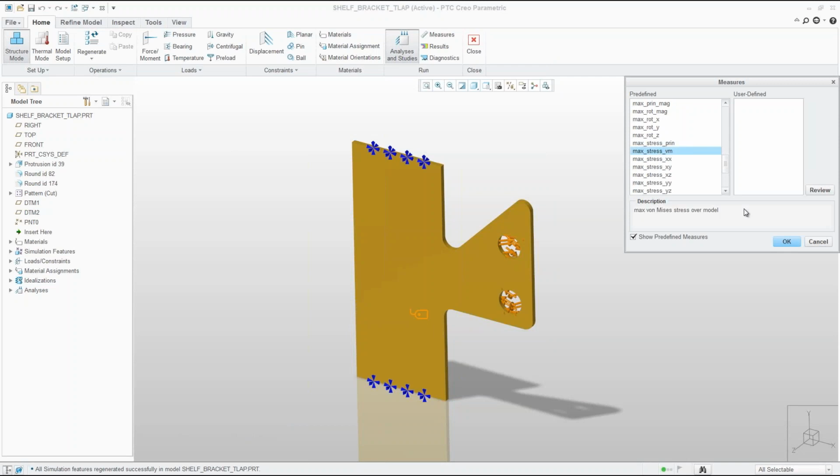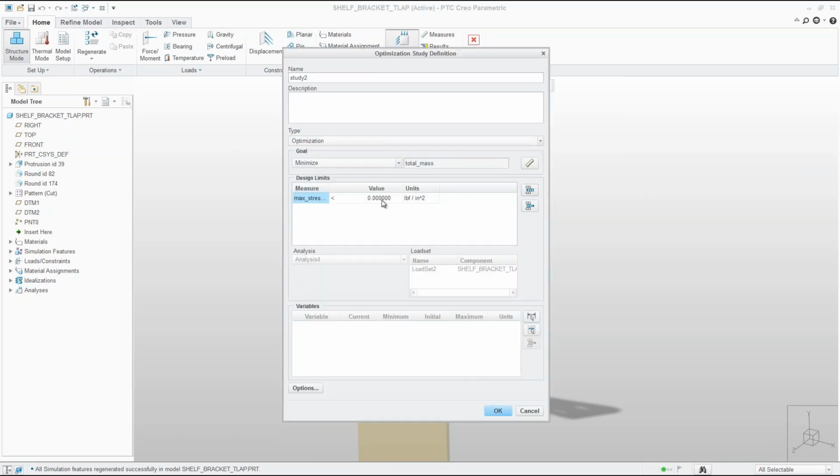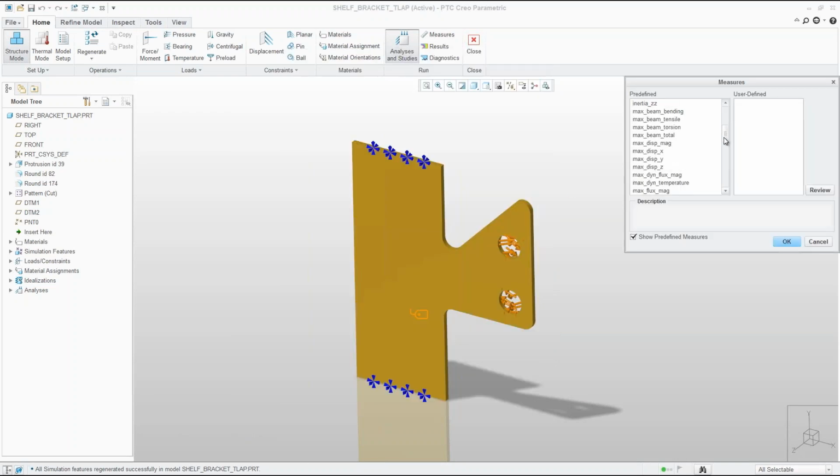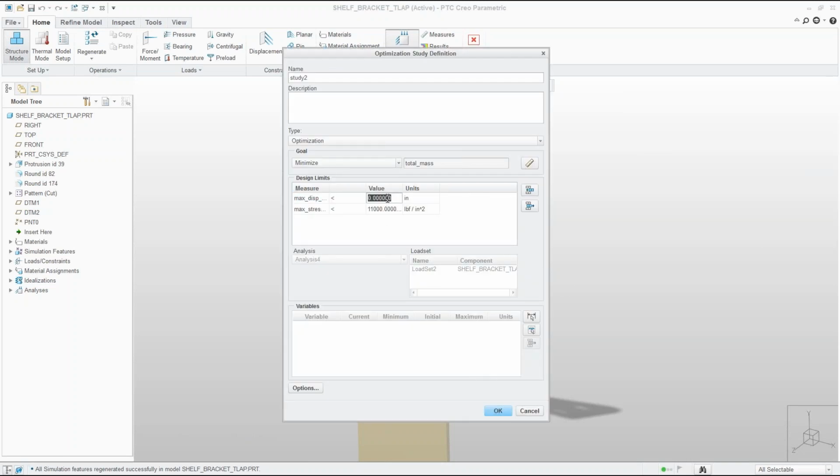And then I want to say, I'm really concerned with the maximum stress. And I have that value that I pulled from that sensitivity study. All these are building off each other. And I have a good limit in mind of what's looking good, where this all plateaued off at. And I might also be concerned with my maximum displacement. That's another value that was floating around in my head, and I know that it can't go past a certain amount for my particular design.